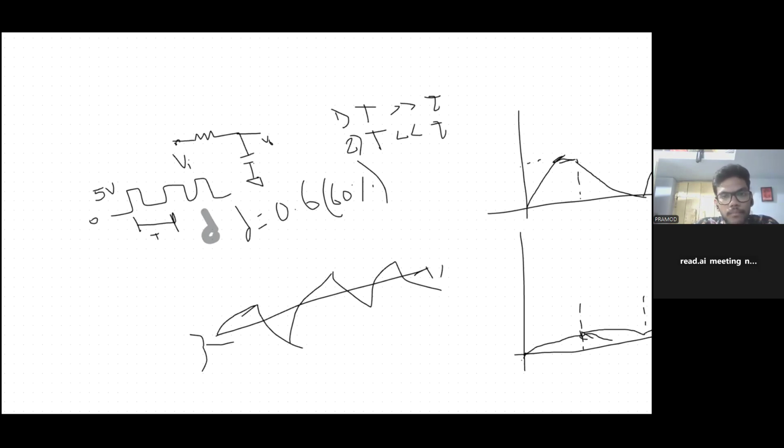Okay, you are saying simply charging rate and discharging rates are same. If you do the frequency analysis, let's assume it is the ideal low pass filter that only passes the DC gains. If you see this point, the DC value, whatever the DC value is, only that is passing. Either 2 or 3, or whatever is there, that will pass.